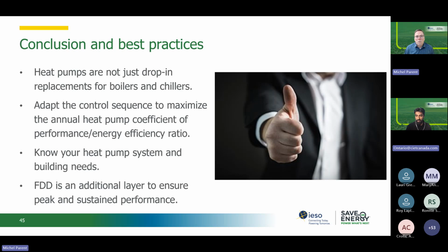And then I see another BS related question. It's a pretty long one, but I've observed that some manufacturers, even though they have a BACnet card on the heat pump, many of the points requiring control from the BS do not provide read or write options to fully integrate into the BS. The OEM controller, in most cases, controls the sequence of operation. What do you suggest to address this issue when more control is required for the BS?